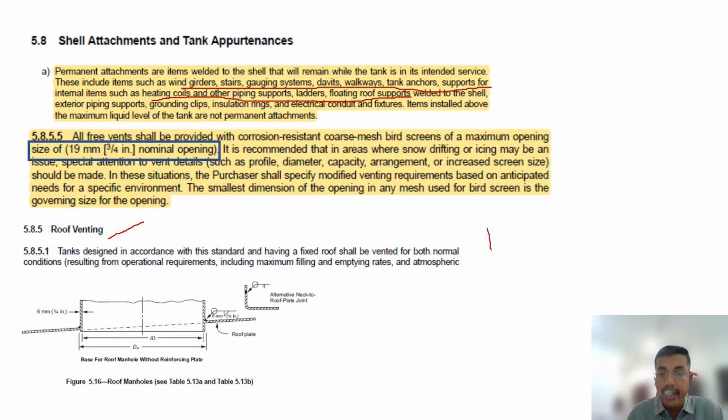First reason why the vacuum happens: if the drainage is not proper and the water is draining very fast, the vacuum will occur inside the tank. Second, if you use some liquid and in winter it becomes solid, and you don't have any arrangement for that, then the vacuum can also occur. Suddenly the liquid becomes solidified and the volume is reduced and a vacuum can be created. So those two reasons are there. For that, roof venting is required.